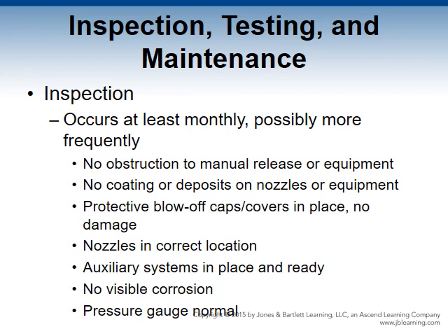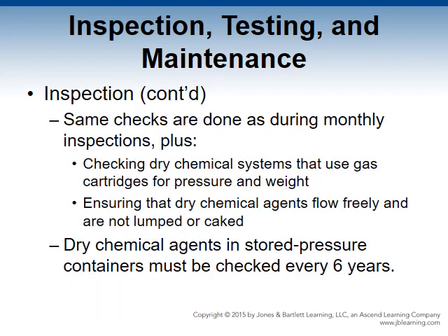Nozzles are in proper location. Auxiliary systems are in place and ready. There is no visible corrosion. Pressure gauge is in the normal range. The hazard process and equipment remains as originally designed, approved, and installed.